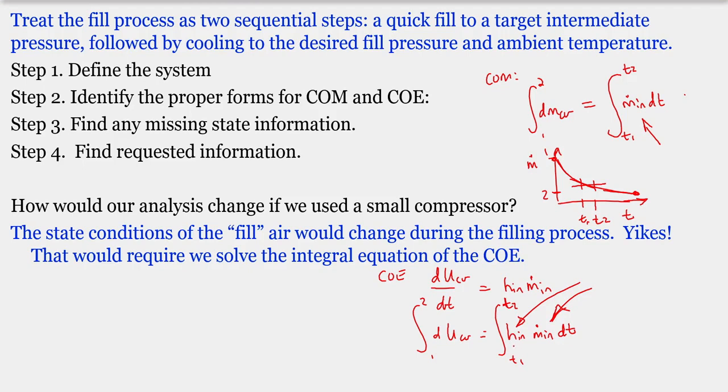So the state within the fill chamber could be changing, and typically we would say, okay, we'd look at how the enthalpy changes as a function of temperature. So how does the temperature within the tank change as a function of time? And we'd have to have that convolved with the mass flow rate changing as a function of time. So you can imagine these get very sophisticated, these transient analyses with not just time varying within the control volume, but these fill problems or draining tank problems also become very complicated when we consider the system to be changing during the process that we're concerned about.